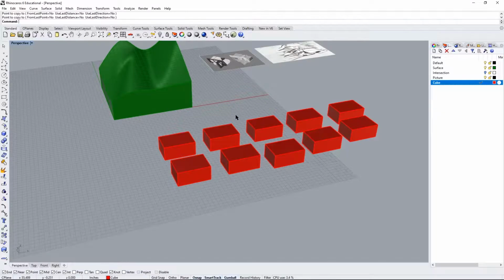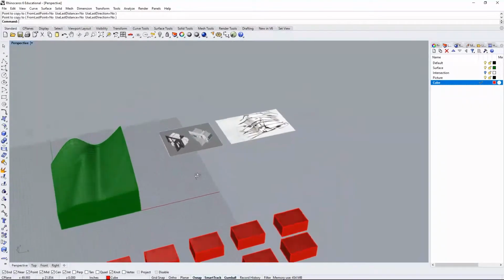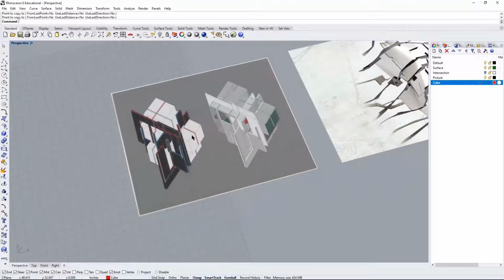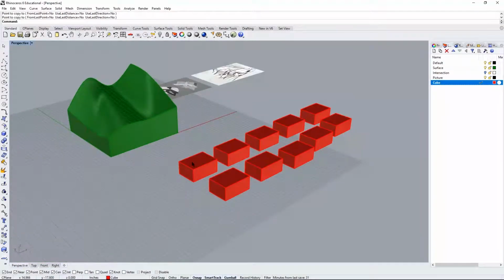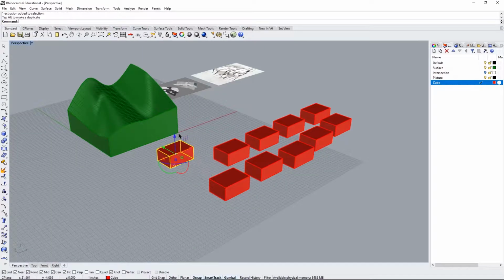And what I'm going to do is use this poly surface over here and have these cubes subtract away some space or volumes from it, because if we imagine this as a fully defined cube, we can see that there's a lot of voided area that is subtracted from it. So we're just going to try to cut a few of those larger sections out. And how I'm going to do that is we can move these cubes with our arrows.